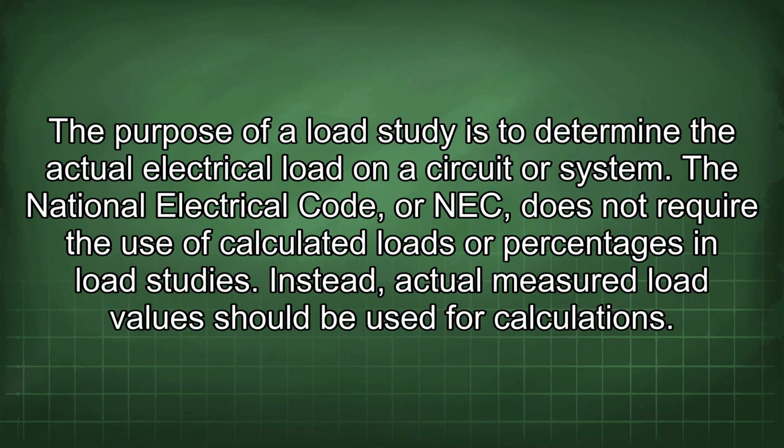The purpose of a load study is to determine the actual electrical load on a circuit or system. The National Electrical Code, or NEC, does not require the use of calculated loads or percentages in load studies. Instead, actual measured load values should be used for calculations.